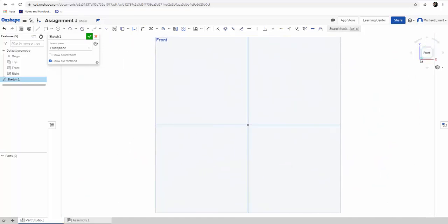So now that we're looking at where our sketch is, and we see the origin, so we can line everything up on the origin. Remember, to define things, we need size and location. So I'm going to start with that bottom line. That bottom line was 80. So I'm going to click, and then I'm going to go to dimension, so just click the letter D. Dimension is this one with the 2 arrows, or you can click the letter D. And we're going to dimension this guy to be 80.